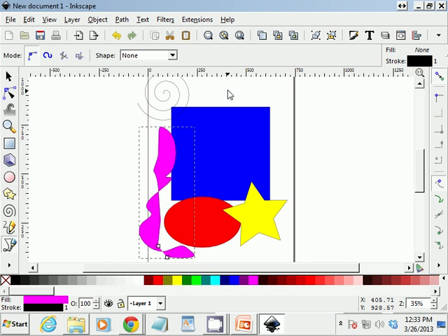In the world of laser cut, by the way, if you do an outline and make it blue, then it cuts it. If you do an outline and make it red, then it makes an etch. So it'll etch whatever you like, if you want to etch in your name or your logo or something like this. And for acrylic that's a millimeter, they won't etch it because it's too fragile and too thin.